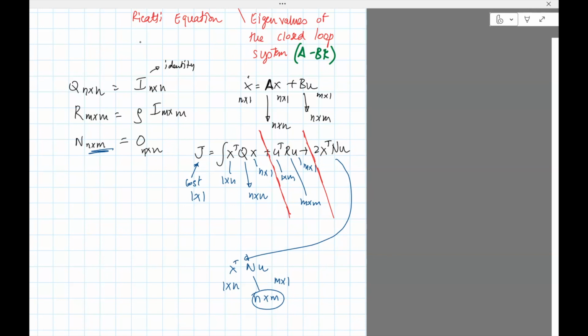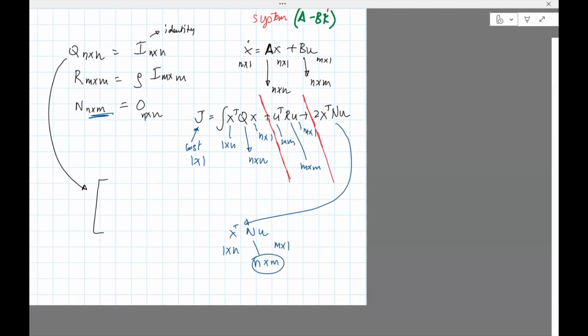Now, sometimes you might have X and X dot with very different scales. If one of them is a state and one of them is temperature, you'll find that this identity will not work. So occasionally, instead of having the identity, people normalize against the maximum value. They'll find the max of X1, and normalize against the max value.